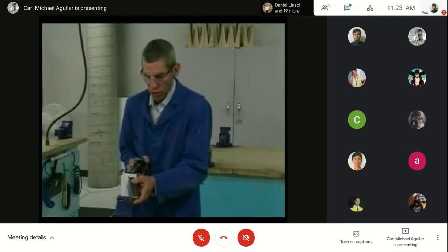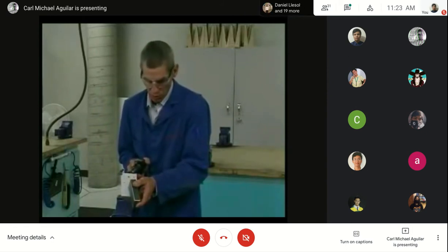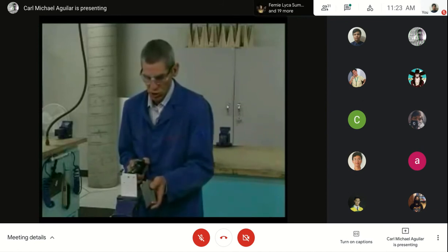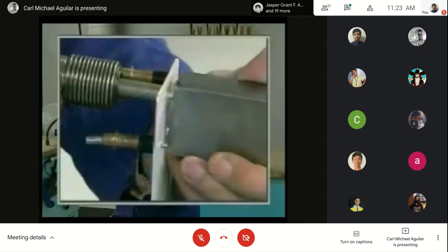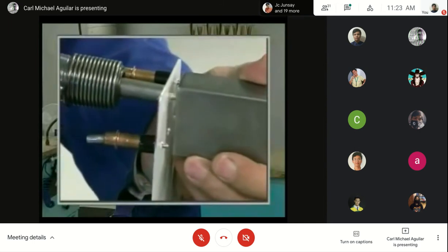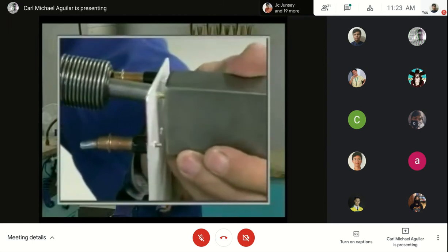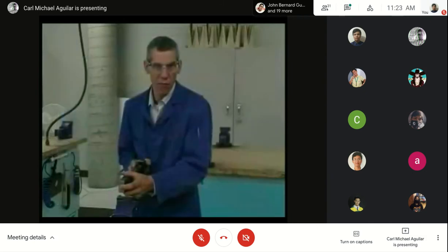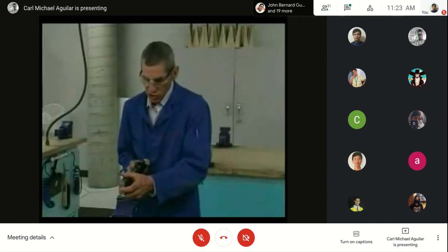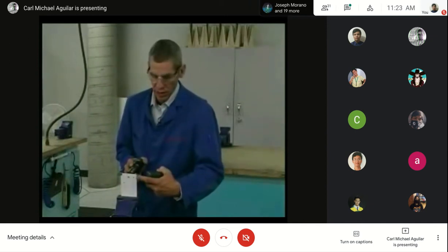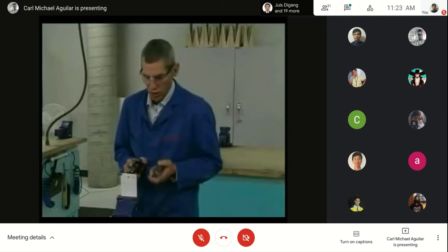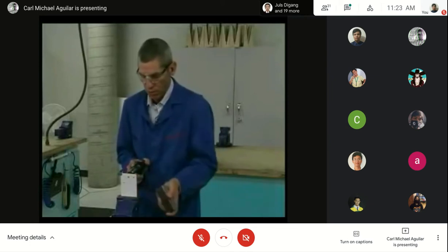How I make sure that I'm pushing hard enough on the rivet gun is that, before starting the riveting process, I am pushing the sheet so it's bending slightly in this direction with, say, 2 pounds of force, and the bucker on this side is pushing back with 1.5 pounds of force. Or if I'm pushing with 4 pounds of force, they're pushing back with 3.5 pounds of force on the other side. So there's just a slight bit more force on this side, and it is evident by a little bit of distortion, the sheet bending in the direction of the bucking bar.